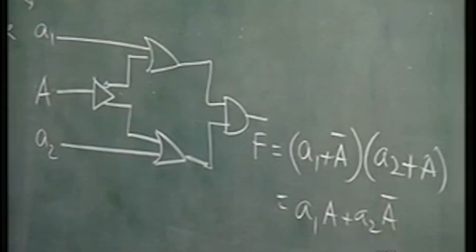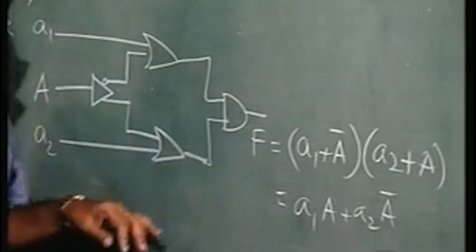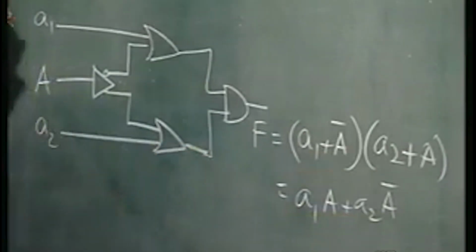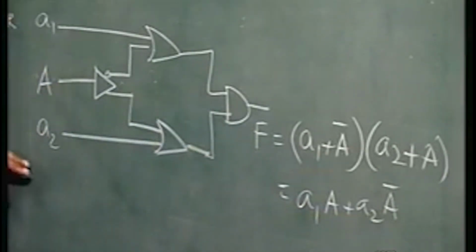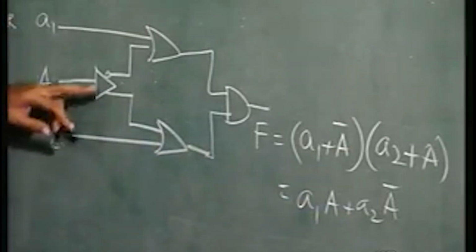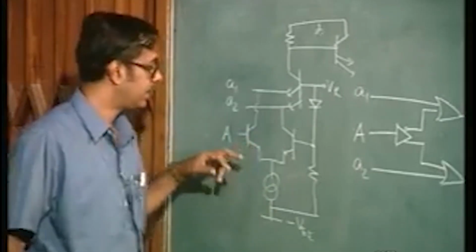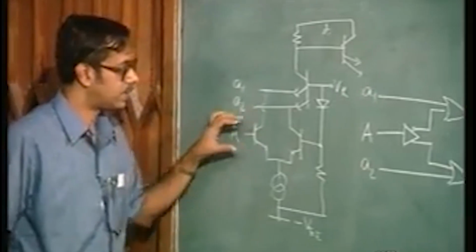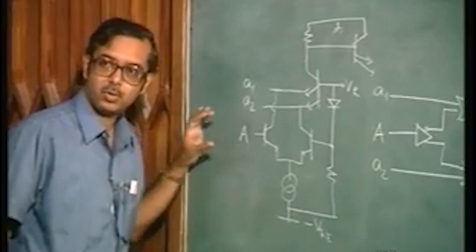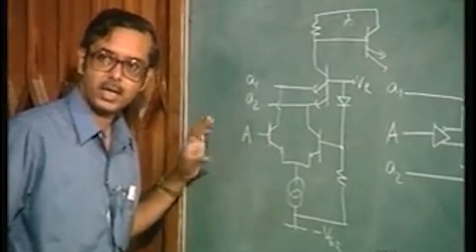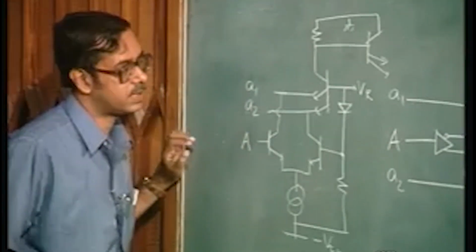All right. So, we have seen this, and this is the logic we achieve, and we have also seen that we can increase the complexity by, instead of having an inverter structure here, having a NOR structure. That is, if you have more transistors in parallel, that is more number of control inputs, you can increase the complexity that way.